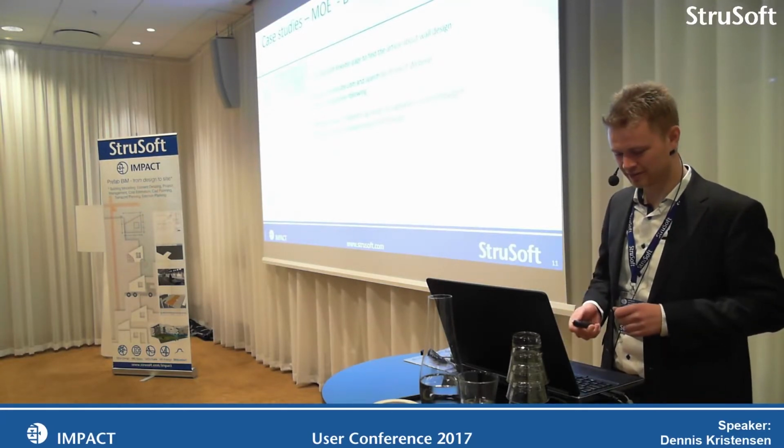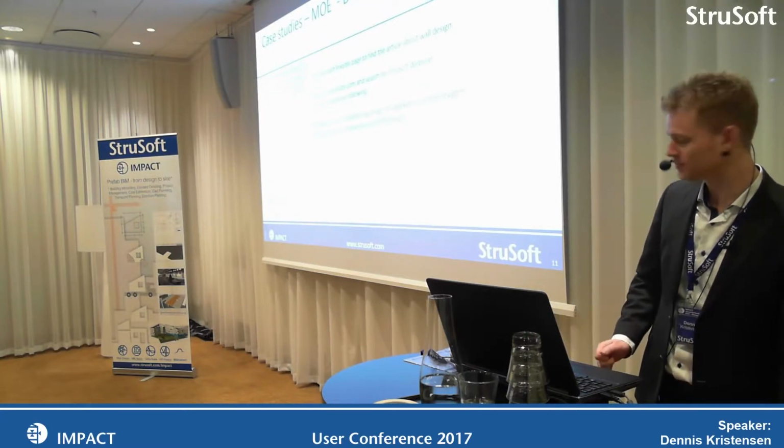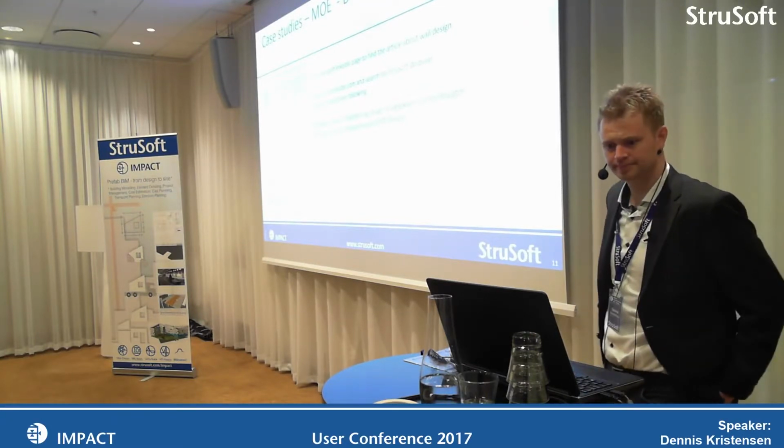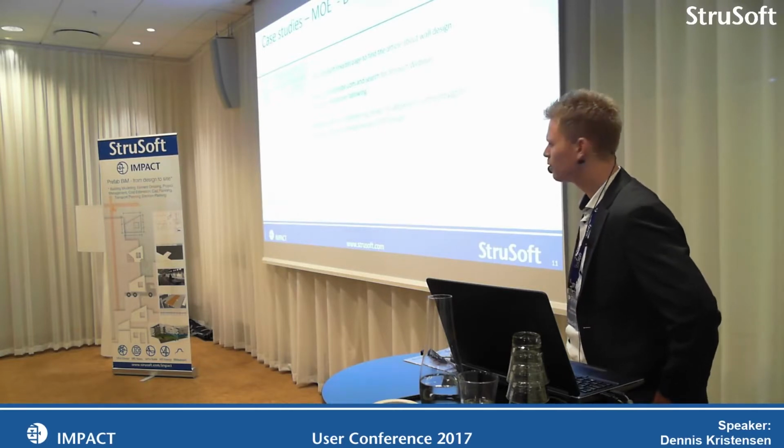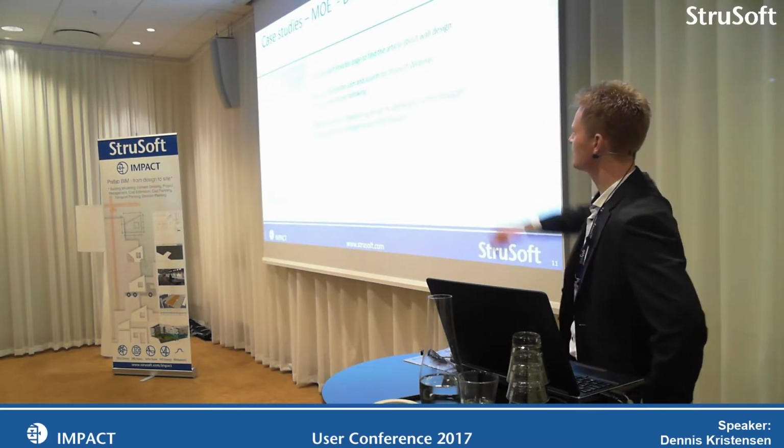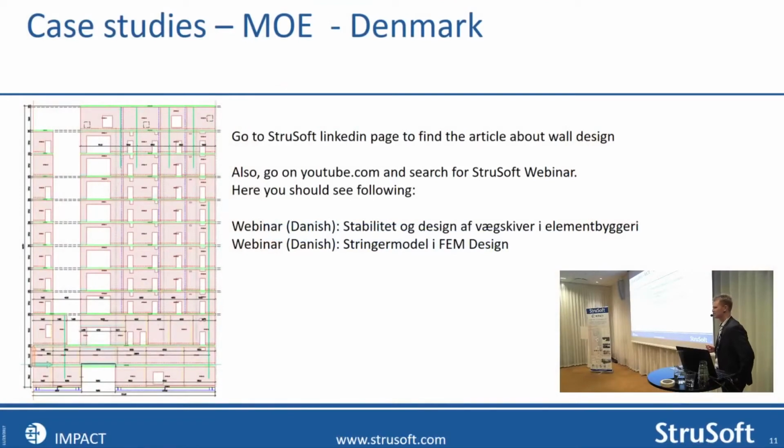A case study of how they designed the precast walls is from Mo. We focus a lot on this in Denmark. How do we optimize our structural designs of walls like this? Because the architects, they love to make holes in our walls. And they would love to put them like this everywhere. They don't do it like this anymore. It's history. So now we cannot calculate our pillars going all the way down. We need to move the forces around the corners of the window openings and door holes, and it's a pain in the ass. But we love it in the software industry.